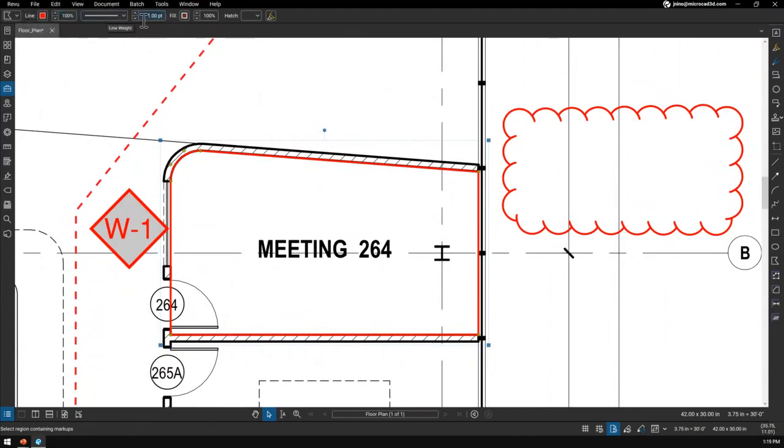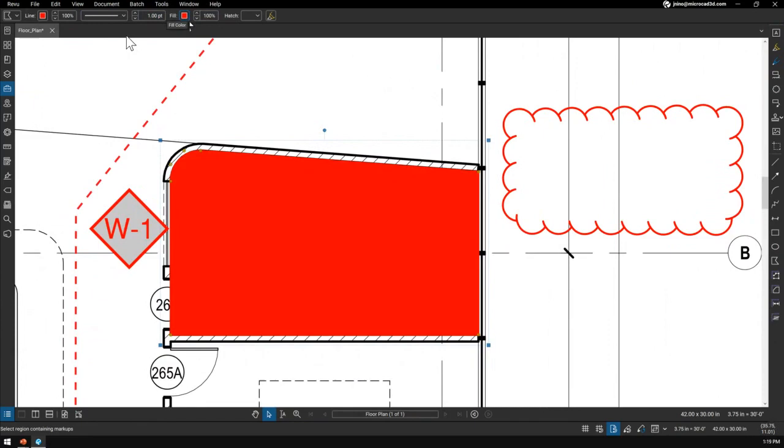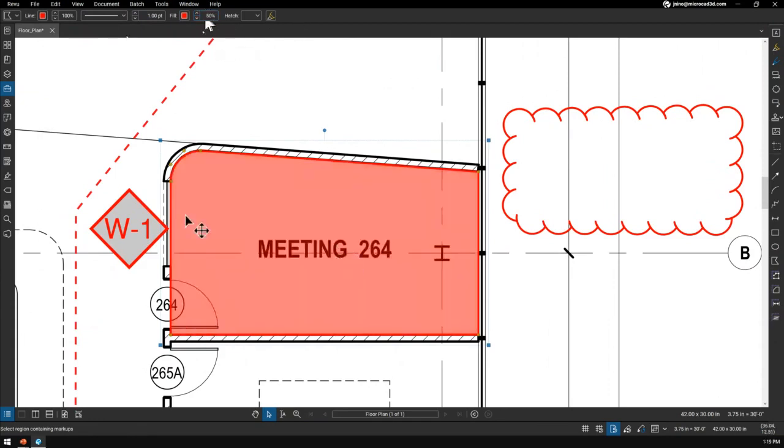So right here, we can start with something simple. Maybe I need to add a field for this room, but probably that is not something that I want to show and share with my teammates, right? So next to that field, I have the option to change the opacity. Maybe I want to have that at 50%, why not? So this is going to highlight my rooms and my annotations, right?